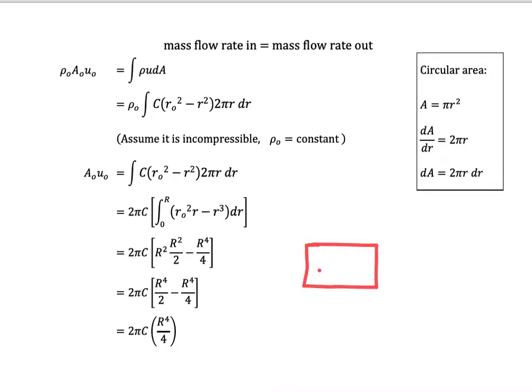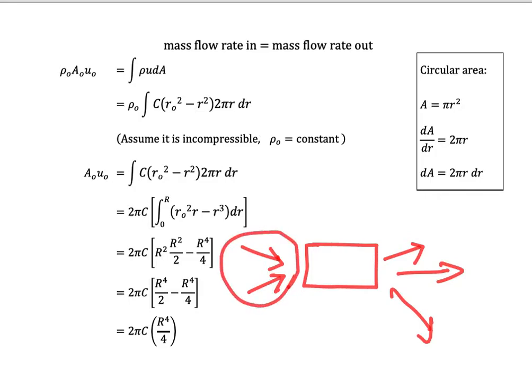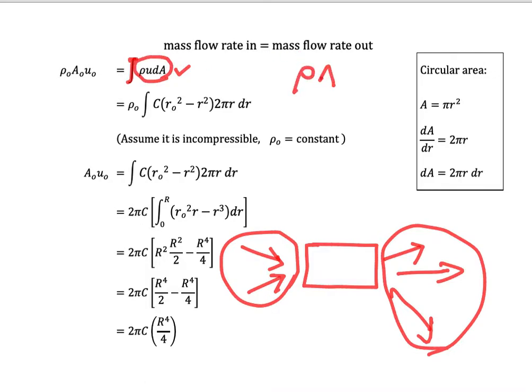The idea is very simple. Normally, if we have a system here, for example, with 2 inlets and 3 outlets like this, we need to sum all the inlets and all the outlets. Normally the outlet is shown with an integral symbol like this one. So how could we start this calculation? We see the equation for mass flow rate is rho A V.